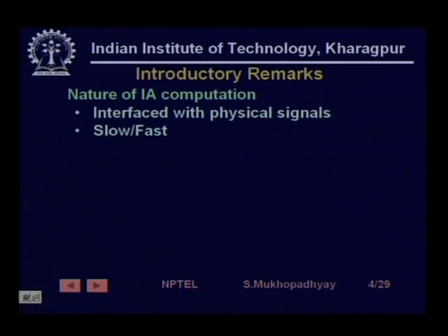The computational requirements of these tasks, by the standards of other applications using computers, let us say digital communication or personal computing, are generally called slow, generally should be slow, although among themselves there could be tasks which are very slow. For example, temperature control tasks are very slow, having time constants of the order of minutes. Let us say flow control tasks would be faster, and if you have a machine control, or you have to have